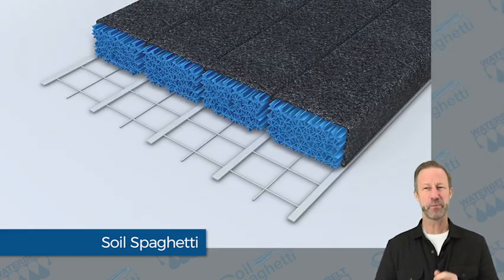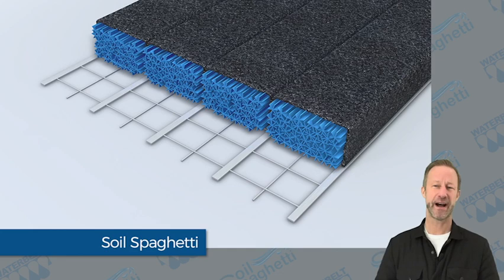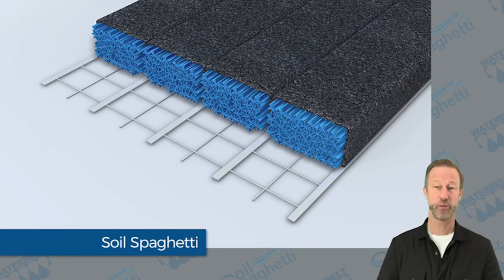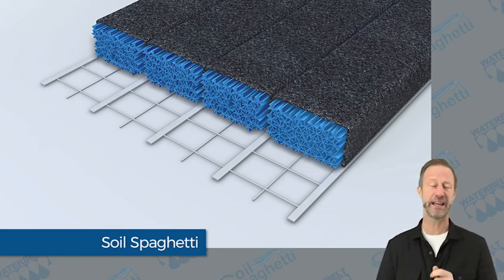A segmented board configuration is ideal when a high capacity, high compressive strength coupled with the ability to transport the collected water without pipe is required. Typical applications include road beds, railway beds, where there's a pumping as the train cars pass, airports, and complex civil engineering projects.